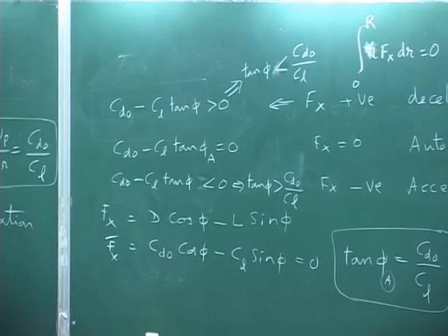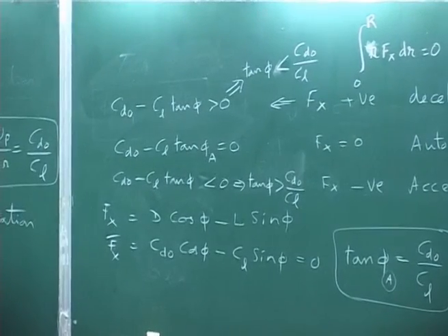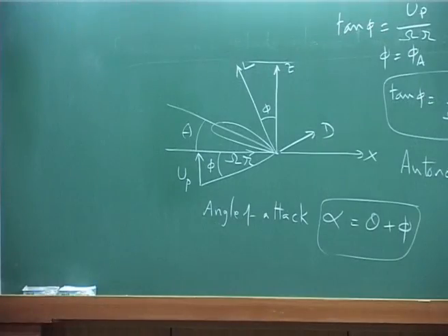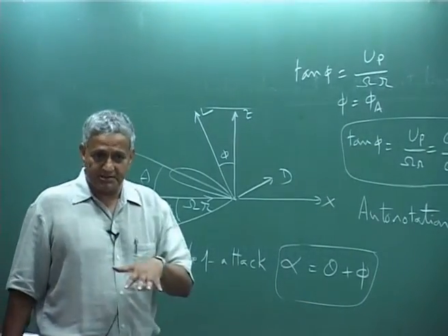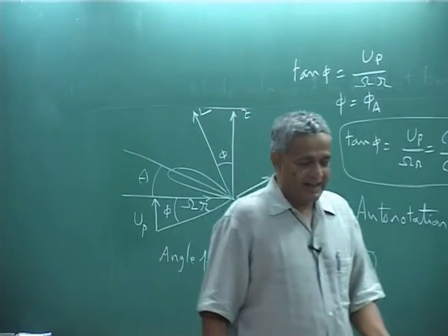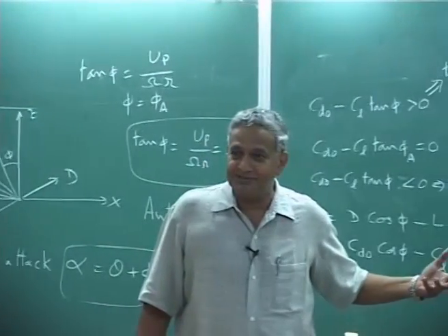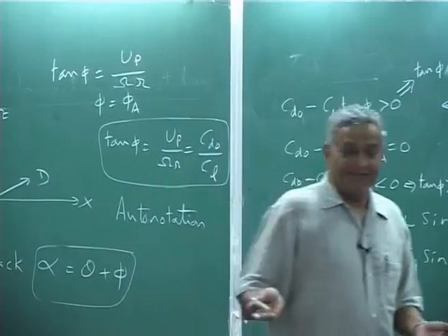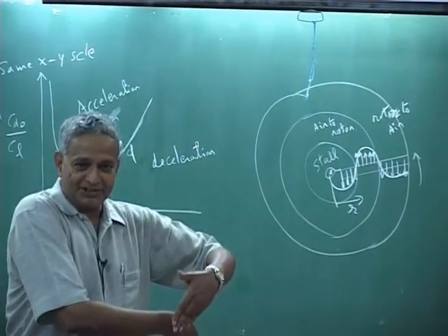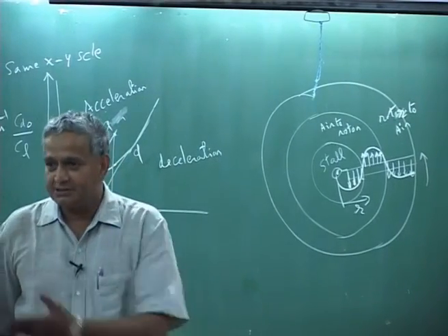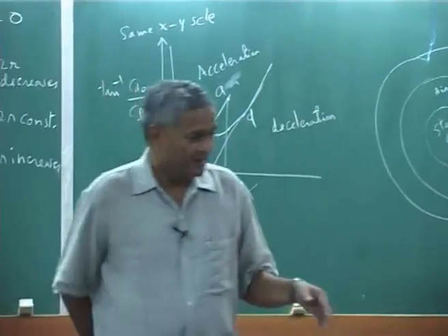Now you may ask a lot of questions, how do I know what is my UP, because UP consists of descent velocity and an inflow. I do not have a clear definition for inflow in the turbulent wake state. I have in the other state, windmill brake state, but not in the turbulent wake state.